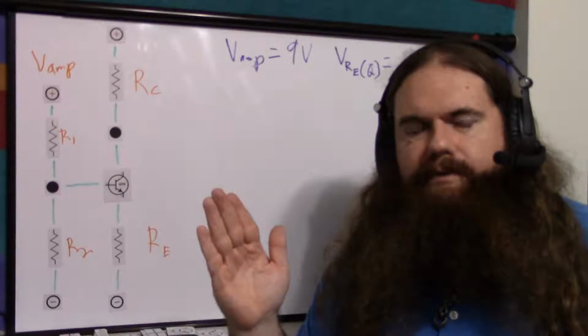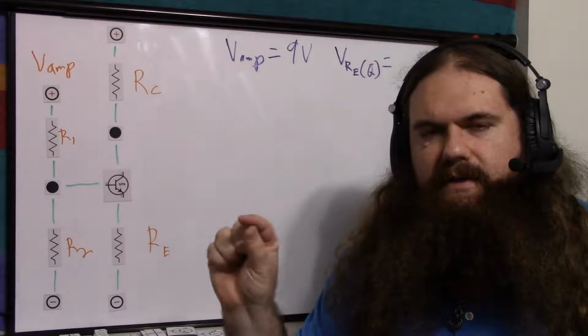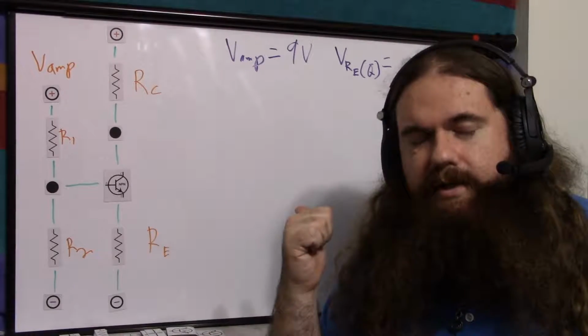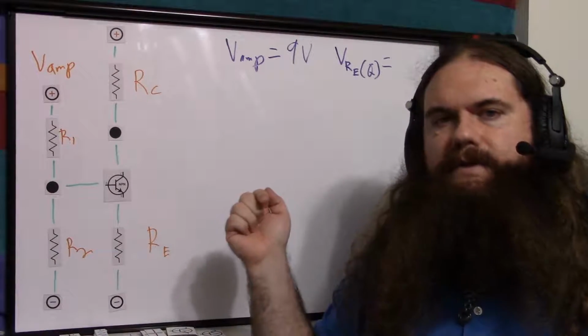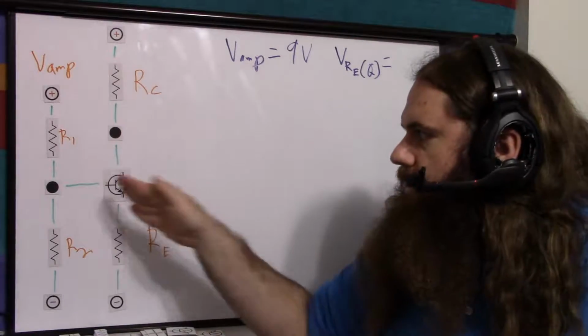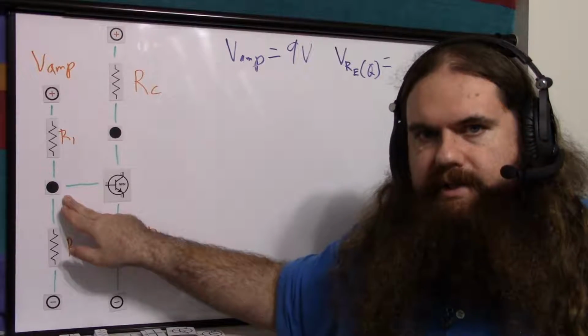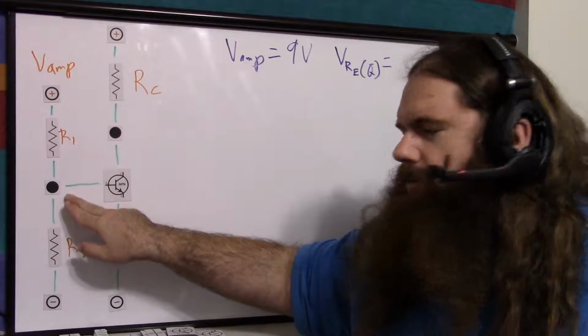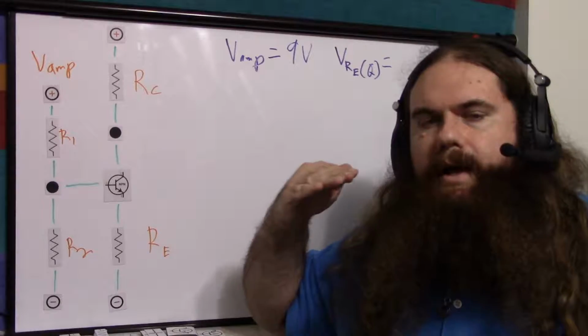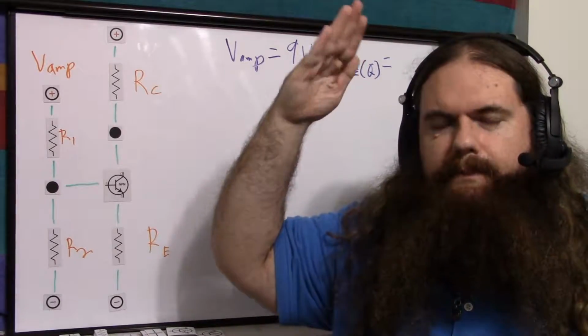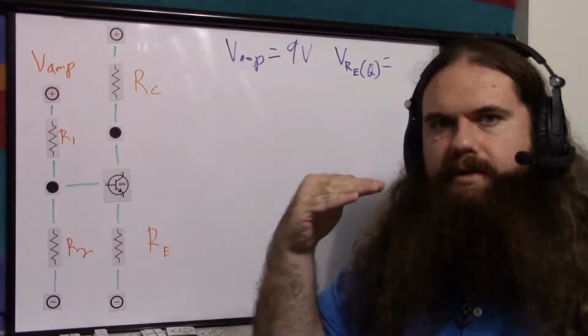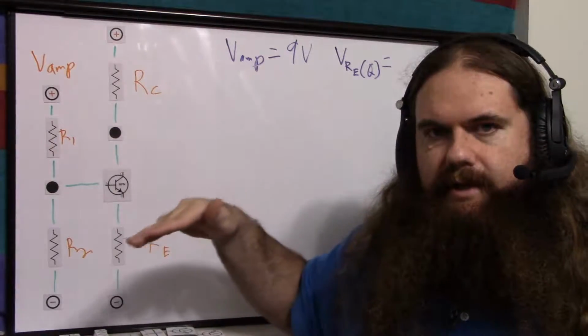So the bias is whatever voltage, and then if you have a positive signal, it'll add to that and increase the voltage from the bias, and if it's a negative signal, it will decrease the voltage from the bias. So a 0 signal or an unplugged signal are the same thing. So this is just always 0 signal. And we work with this because the signal will go up, the signal will go down, but it's centered on this point. So we want to do the centering based on that.